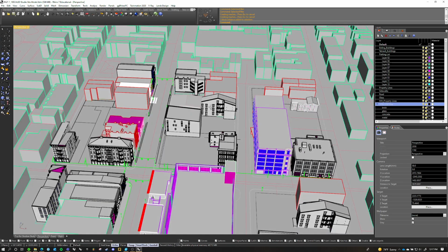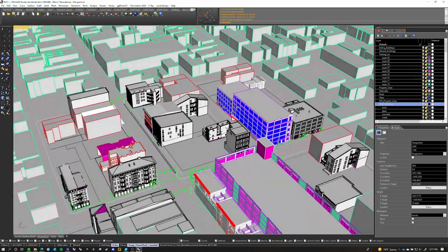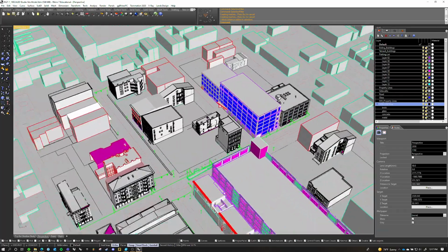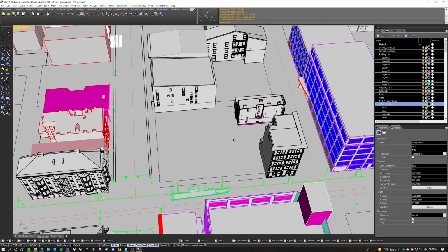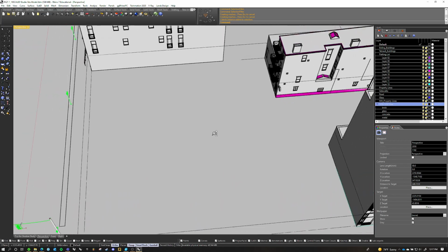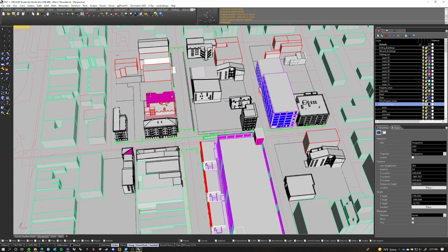So right click is how you move your camera around. Your mouse wheel will zoom in and out. And then two helpful navigation commands that I know are, if you hold control and right click, you can have a more controlled zoom to a specific area, which I think is very helpful.